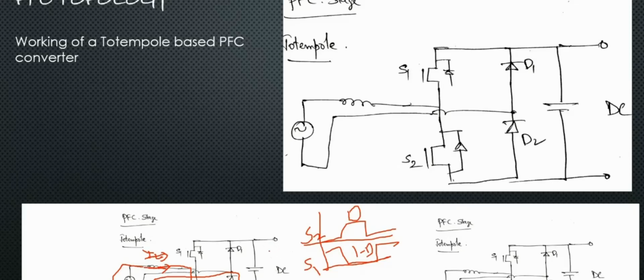So what essentially happens is on the DC side, there's no question of power factors or anything. Voltage and the current are in sync, right? All that we need to ensure is the current through the inductor is in sync with the voltage. So in the logic, the VAC should be exactly in phase with the IL, or the other way around. The IL should be exactly in phase with the VAC.